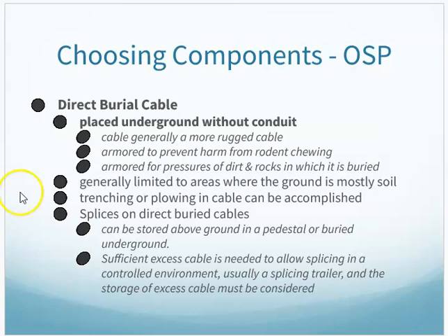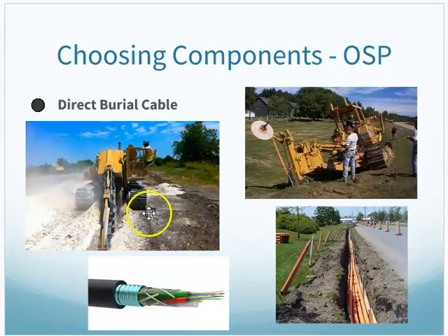Direct burial you can place without any conduit, but I need to make sure I have the correct type of cable to do so. So I might actually be doing a trench. And there's more than one way to do it. This kind of reminds you of a giant ditch witch, like a big saw that you're going to dig a trench in. And then there's a style here that's a plow that you're literally dragging through, and as it goes, the fiber's getting laid in there.